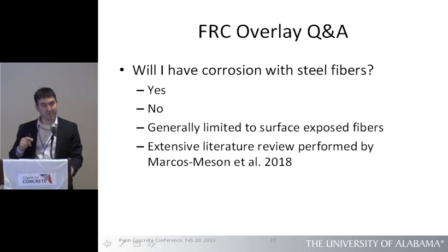And by far the most common question, especially with steel fibers, and especially up here in the, well, I call it the north, where you have de-icing salts, will I have corrosion? Well, yeah, because you're throwing salt on steel, it's going to corrode. But turns out, and we see this in Chicago, because there's a lot of steel fiber reinforced pavements, that only the surface fibers corrode. And then they break off. They don't puncture tires or anything. They just corrode away. And then the interior fibers are generally non-corroded.